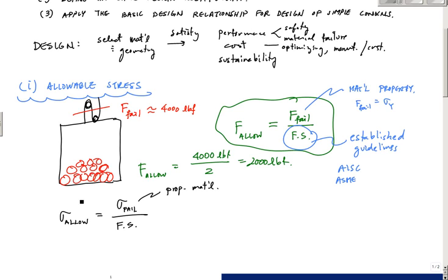And normal stress is just one way that a material can fail. Something can also fail in shear, and so we would have an allowable shear stress as well. And then we'd have either shear yield or shear rupture, for a bolt or something, and then a factor of safety to control what we can allow, right? And obviously, because we're making sigma allow less than sigma failure, the failure load or whatever it is, the factor of safety is typically going to be greater than 1. That's what you'll normally see. This factor of safety is greater than 1.